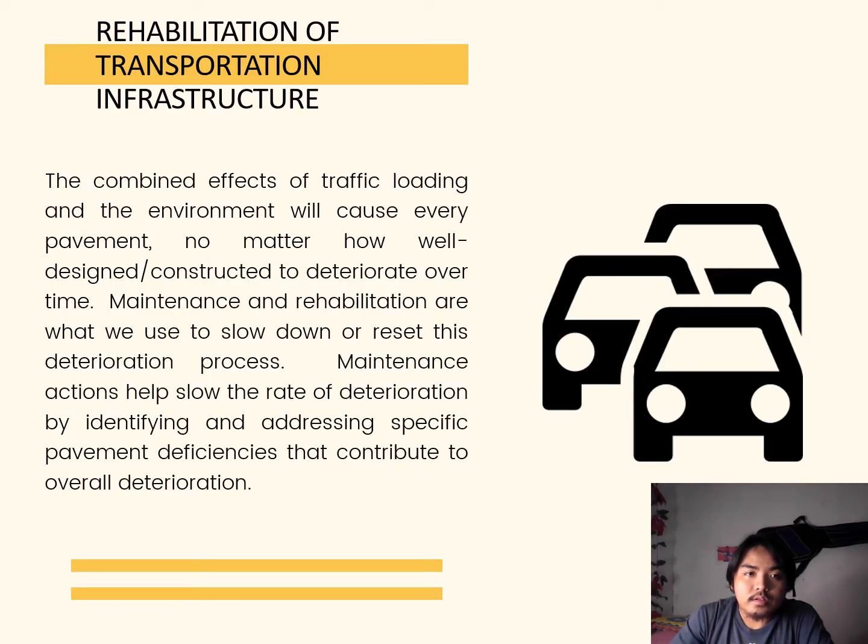The combined effect of traffic loading and environment will cause every pavement, no matter how well designed or constructed, to deteriorate over time. Maintenance and rehabilitation are what we use to slow down or reset this deterioration process. Maintenance action helps slow the deterioration process by identifying and addressing specific pavement deficiencies that contribute to overall deterioration.